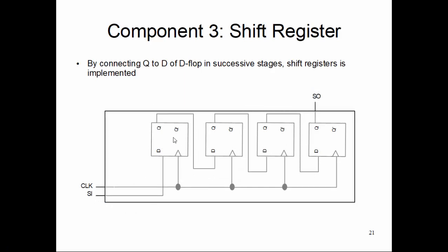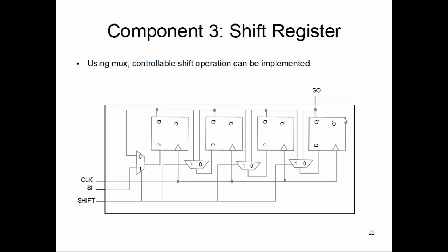Now, is there a way I can selectively pick up some incoming bit? Otherwise I'll hold on to this bit pattern, whatever is happening right now. So we can do that. Use a couple of multiplexers there, 2x1 1-bit multiplexers, where scan in goes into the terminal 1 of the first stage multiplexer, and Q from the first stage flip-flop comes back to the 0 terminal of the first stage multiplexer, and the output of the first stage multiplexer goes to the D terminal of the first stage flip-flop.